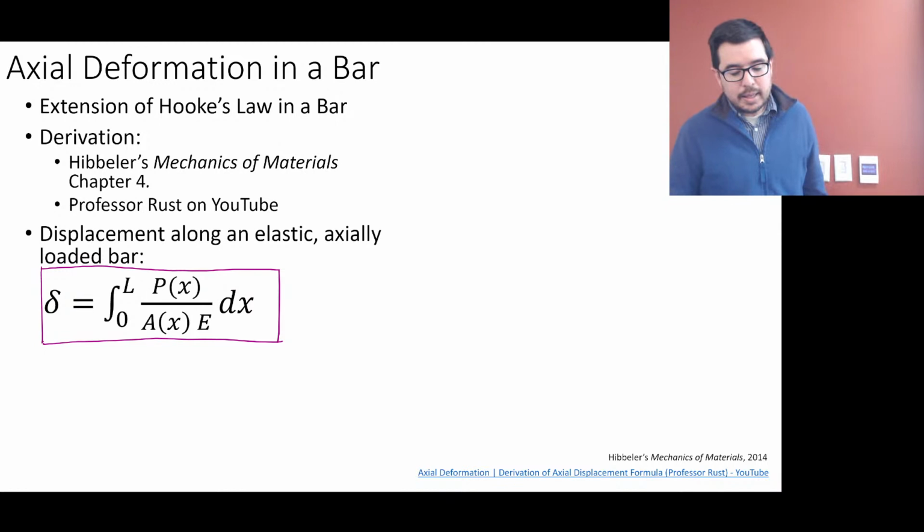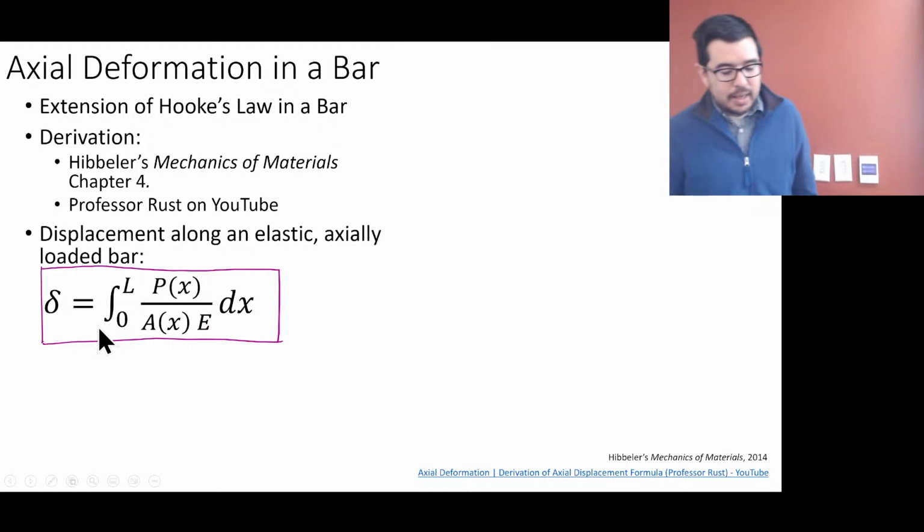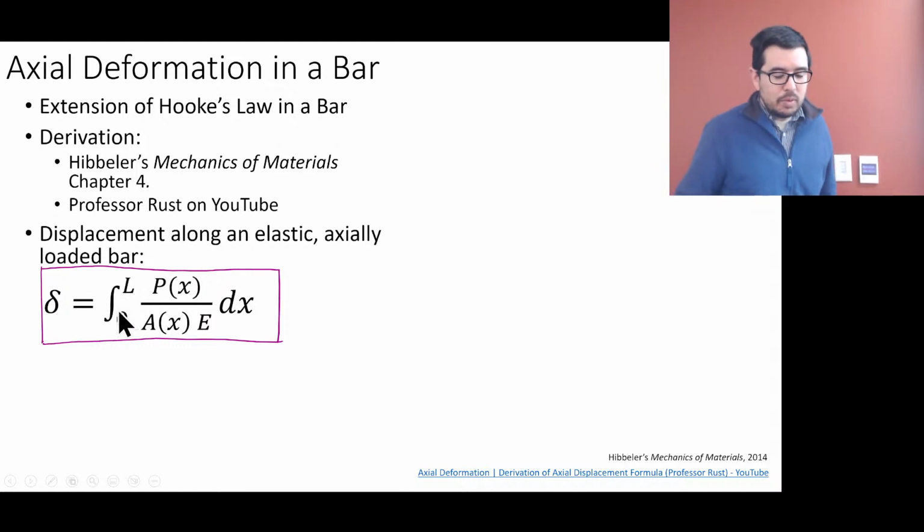So what is this saying? There are a few terms here. If you have an axially loaded bar, and let's say you're going from 0 to L, so you're going along some length, and there's an internal force P and a cross-sectional area A, and the material has elastic modulus E, we can integrate this expression to get the displacement.